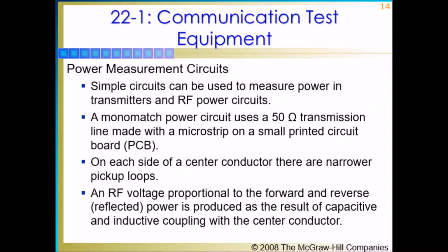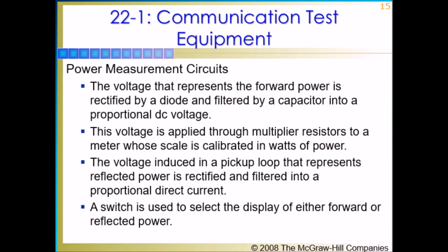A more sophisticated power meter is the bench unit designed for laboratory or production line testing. Power meters may have either an analog readout meter or digital display. The dial or display is calibrated in milliwatts, watts, or kilowatts. The operation of a power meter is generally based on converting signal power to heat. Whenever current flows through a resistance, power is dissipated in the form of heat.